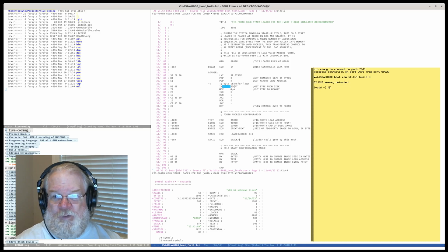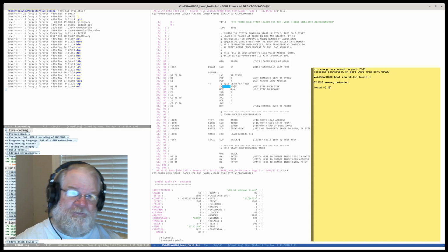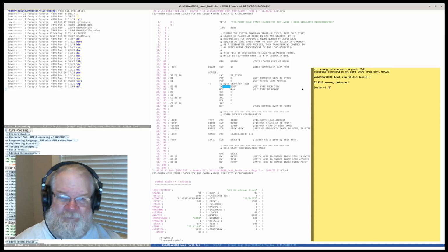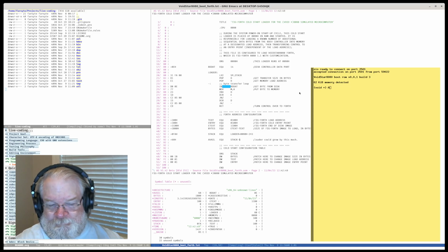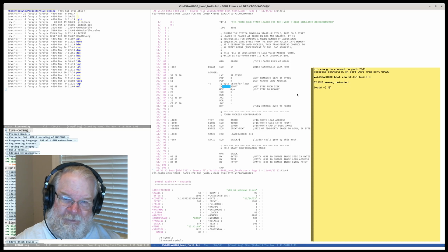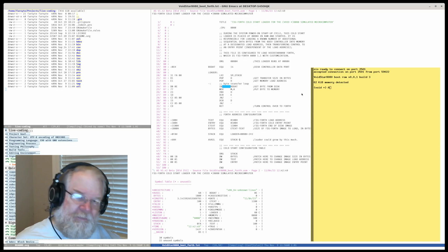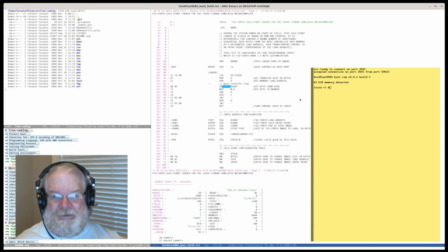So normally in a PIO situation, you would read a status word that says, "Are you ready yet?" And at some point, the status word would say, "I'm ready," and then you would start moving bytes. Or for any number of reasons, what you would really do is give the disk controller a command that says, this track, this sector, put it there, go. And then later you get back an interrupt that says, we're done. Not doing that.